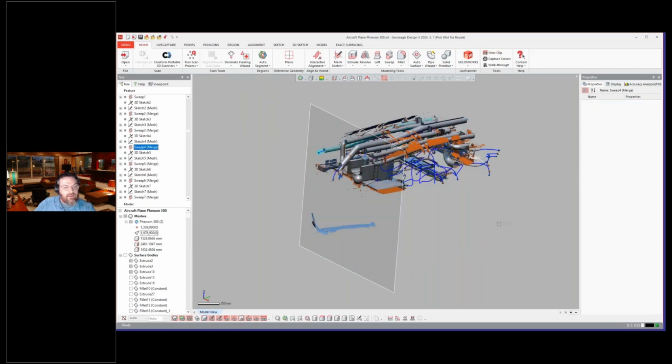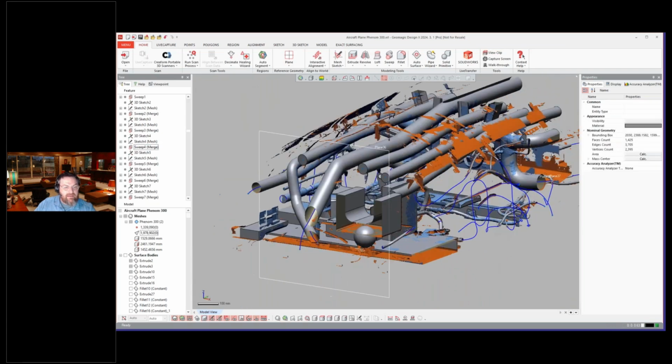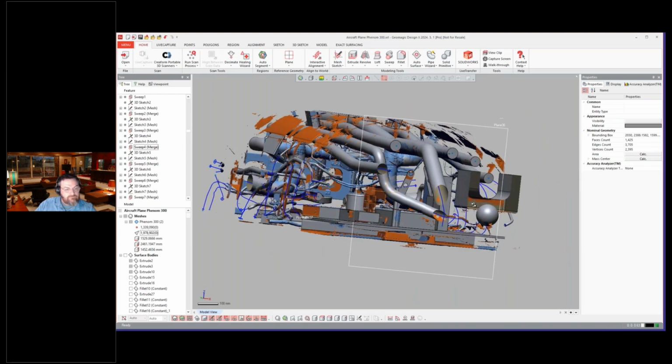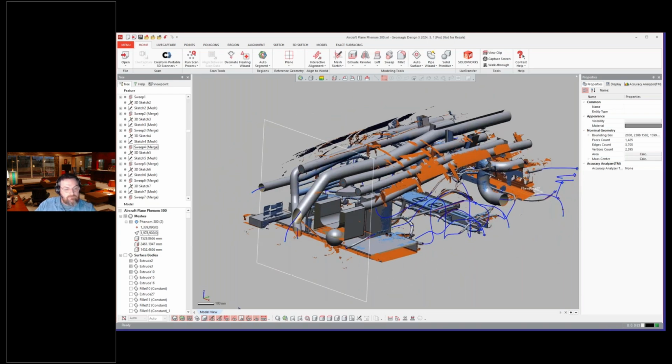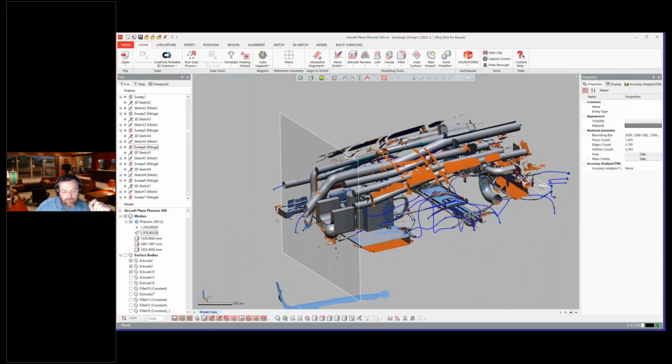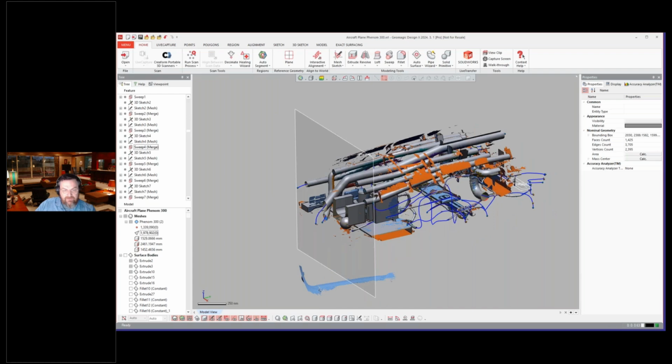And then when I hit OK, now I've limited it to just that area to see just what's there. Right? So that's really cool to be able to adjust the view clip. Now, one thing that's important is view clip is this persistent command that's like on in the background, and it's very easy to forget that it's still on and even open up other files with it still on.